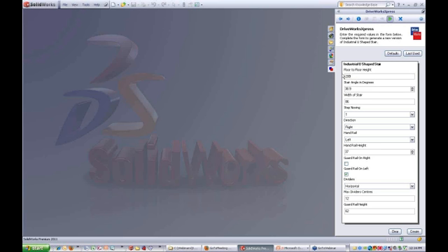Everything looks okay. Next field is the angle in degrees of the stairs. That tells me it's between 32 and 42. It's up to 0.1. Little spin arrows over here. And again, I'm controlling my data. I can go down only as low as 32 degrees and only as high as 42. Again, I'm controlling the data input, limiting the possibility of errors. We'll leave it at 42. Width of stairs, numeric entry again, between 36 and 108. We'll make it 100.